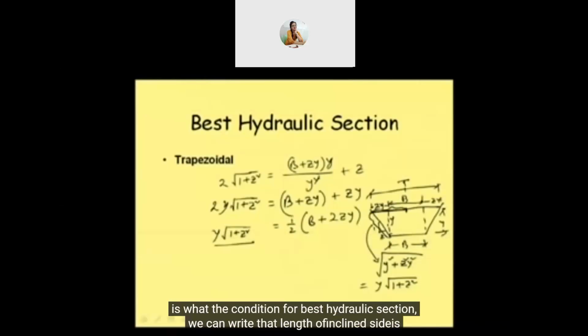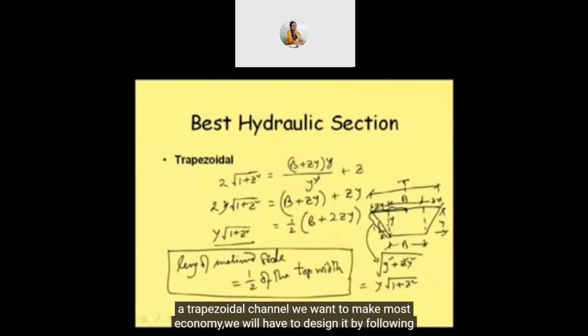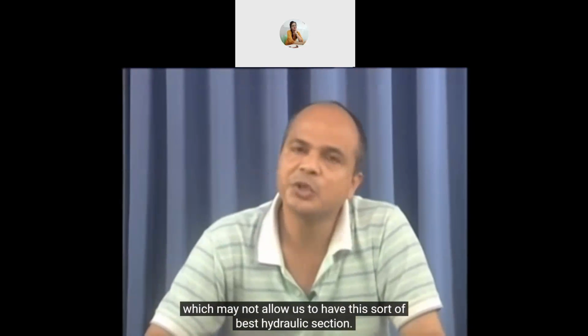We can write that the length of the inclined side is equal to half of the top width. So this is leading us to this condition. If we want to make a trapezoidal channel most economic, we will have to design it by following this concept. Again, we should not forget that there may be a lot of practical considerations which may not allow us to have this sort of best hydraulic section.